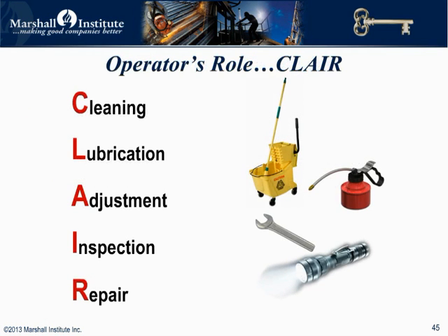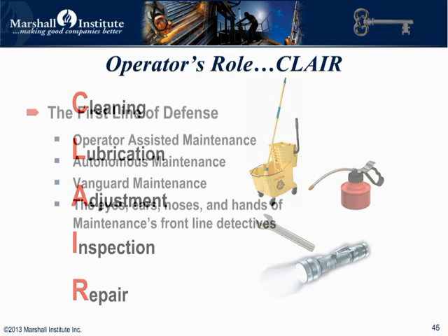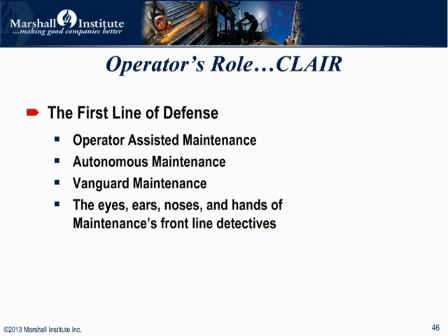Section 5 dedicates a significant amount of time and attention to the importance of operator involvement in maintenance, typically through specific sorts of activities which we at Marshall Institute call CLARE: cleaning, lubrication, adjustment, inspection, and repair. Operators are our first and best line of defense. We should be doing everything we can to engage the hearts and minds of our operators in basic equipment care. They are truly the eyes, ears, and noses of the maintenance function.